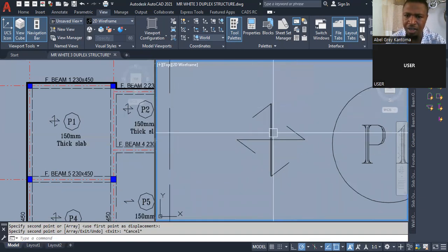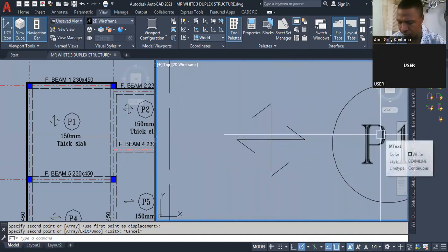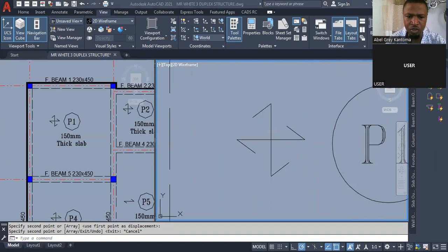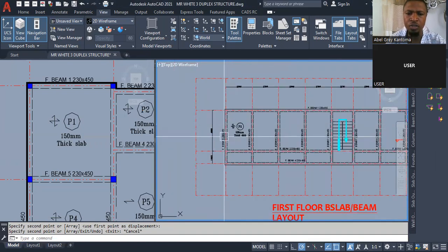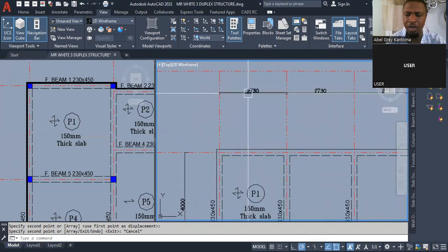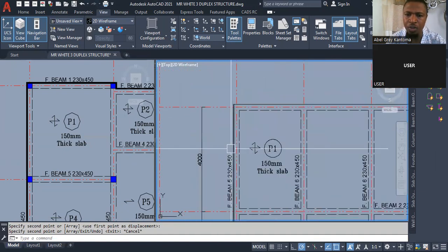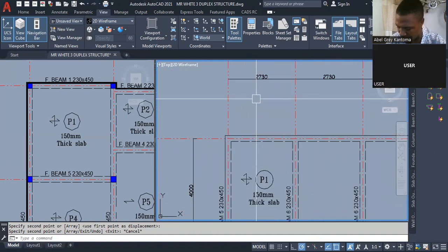So we are going to be having our main bars along this length. We are also going to be having our main bars along this span as well. So let me do the small calculation and show you how to come about that. So all you do is to divide your Ly all over Lx. So your Ly means the long span, the Lx means the short span.